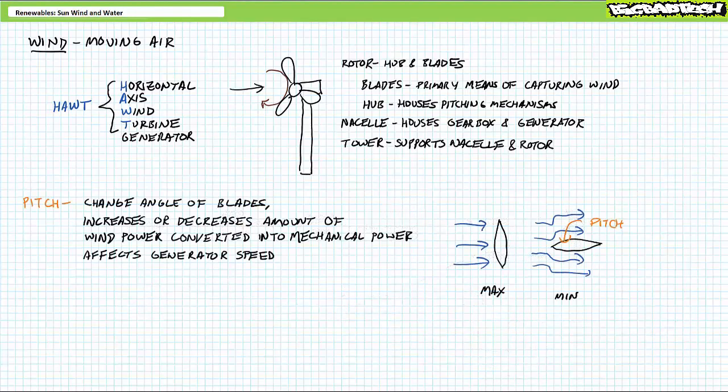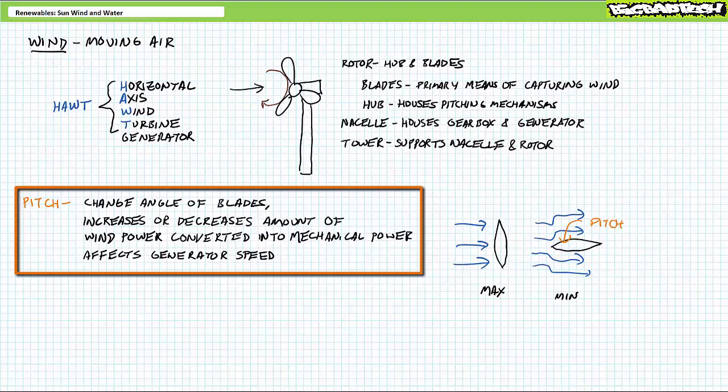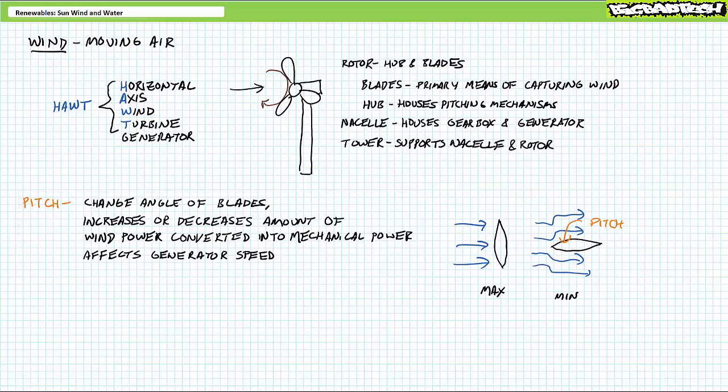Modern wind turbine generators are fascinating electromechanical constructs because they must automatically regulate numerous actuators in response to often wildly fluctuating input conditions. Of primary concern are wind speed and wind direction. Wind speed directly influences rotational speed of the hub, and to keep generator output inside a desired range, the wind turbine actively pitches, or changes the angle of attack of the blades, using electrical or hydraulic actuators such that more or less of the blade is exposed to wind, thus capturing or shedding more or less of the incoming wind. Think of each blade as one uses a canoe paddle. Oriented in one fashion, maximum exposure is achieved, yet oriented in another, the blade slices cleanly through the water, or in this case, air.